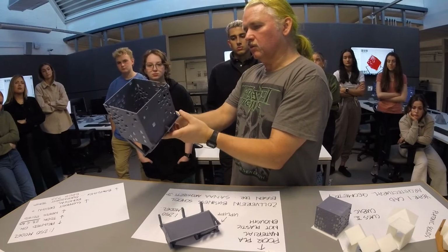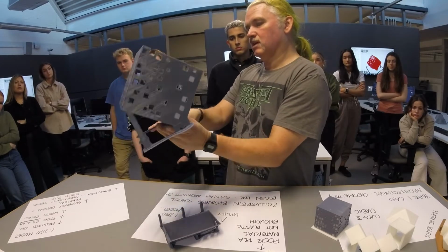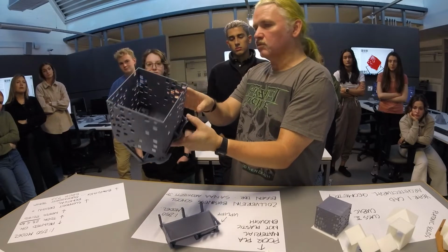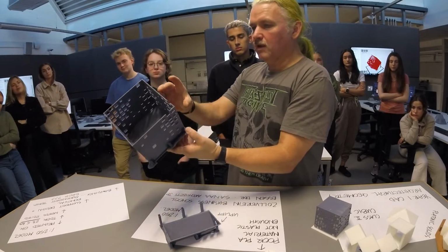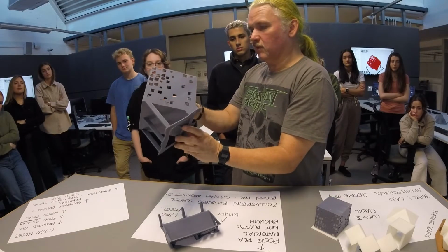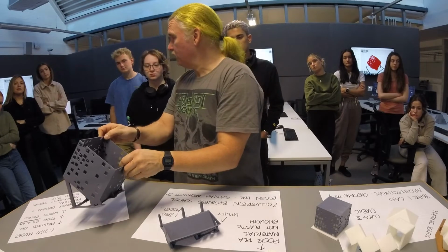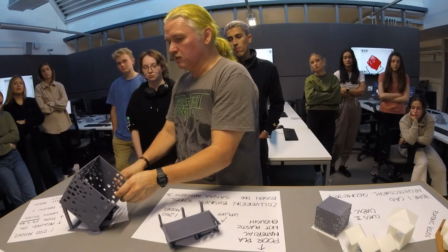And the only thing I can think of is that it was during the day up to then, and then it went into night time. So the temperature in the room gets colder, and it does affect the behavior of the print. You have to watch out that the machine's not in a draft or something like that, because it really does not like that.